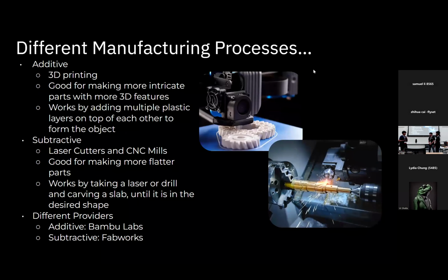Now, we can CAD complex things, but fabrication is just as important. There are 2 ways that you will manufacture things to get a part. First is additive manufacturing. This is using a raw material like plastic filament to make a complex and intricate product, like a clock. Another is subtractive manufacturing, where you take a body and remove material from it. That is something like CNC milling or laser cutting.